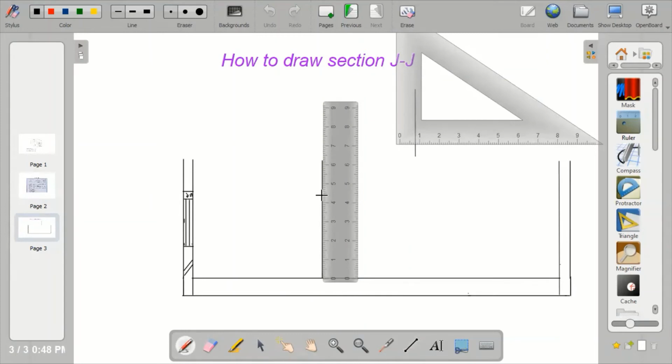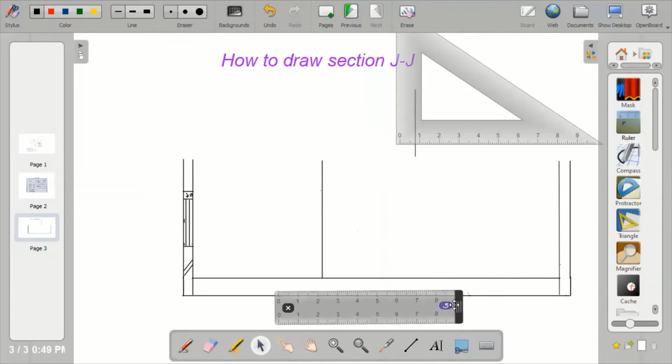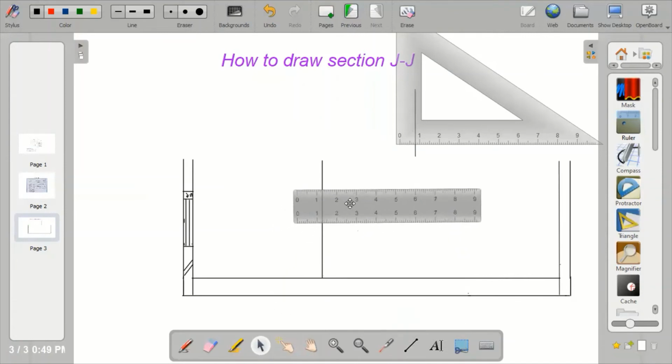4,700. So I'll put a dot at this point. Then when I get there, I'll just fix my beam. So in this case, I don't need to draw my wall from the floor level. I'll just fix my beam at this point. But before then, I'll bring out the wall thickness because I'll need it above and not below. So I'll bring out my wall thickness, which is 450, like we did for the first one. It's 450. I'll put a dot to bring it out.